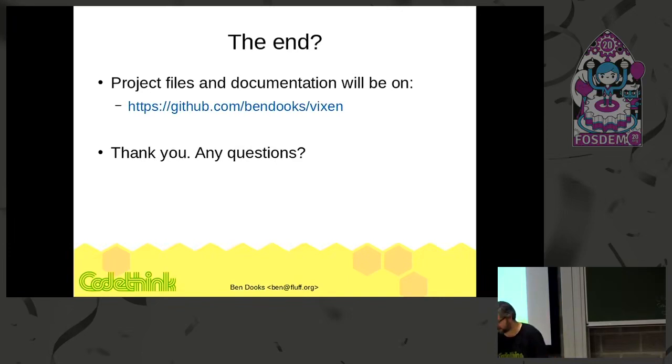There's a couple of questions here. Firstly, the module I've chosen has a certain amount of selection for the memory, and where it says it's a 16K, there's a 3K module mode. The first easy bit is I couldn't get the switches, so I just used jumper headers to replace them. Now the memory map of the VIC-20 already has 5 kilobytes of memory in it. There are 2 8K selectable areas, and the jumper just changes which of the chip select lines are fed into the logic of the Vixen.